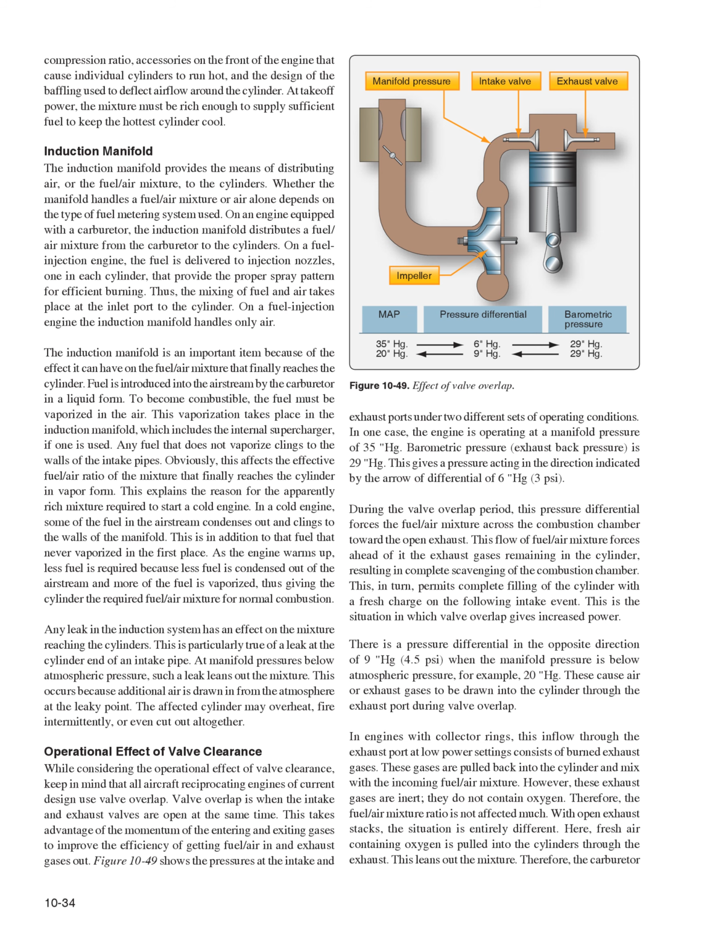This explains the reason for the apparently rich mixture required to start a cold engine. In a cold engine, some of the fuel in the airstream condenses out and clings to the walls of the manifold. This is in addition to that fuel that never vaporized in the first place. As the engine warms up, less fuel is required because less fuel is condensed out of the airstream and more of the fuel is vaporized, thus giving the cylinder the required fuel/air mixture for normal combustion.